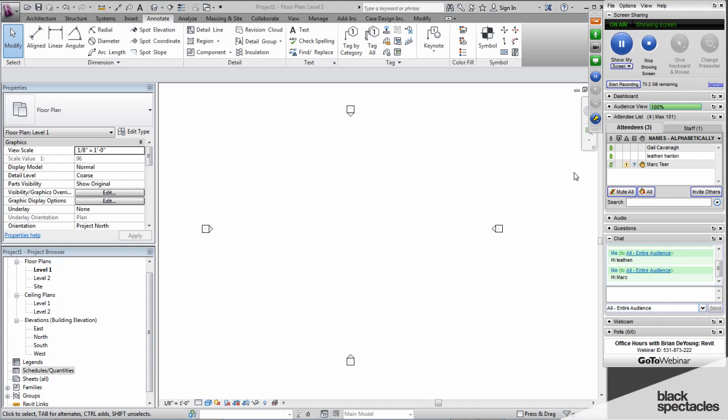They are linked together. If you're familiar with CAD and AutoCAD, it's a similar process to an XREF. So, for a typical project, you would create, for example, a site file. That site file would contain the topography. If there's anything subterranean in the project, you would create a pad that would basically create a pit for the building to sit in. You would put all of your sidewalks and roads and context into that site file, but that's all that you would have in it. You would not build any buildings in that file.